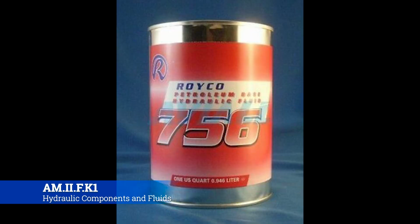Okay, so the oldest and probably one of the most common hydraulic fluids out there is Mil-H-5606, or commonly referred to as 5606. Now, the picture you see up on the screen right now is a Royco 756. It's just Royco's product that is 5606.